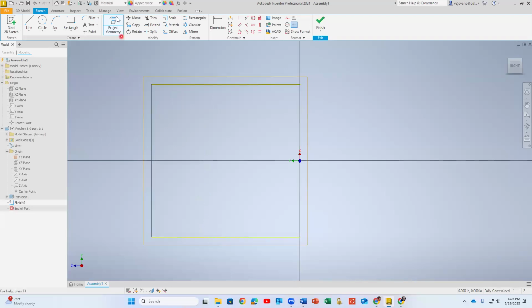And then before I use them, I can turn this off by either clicking one more time there or Escape. So you see, I no longer want to do that, or you click somewhere else on something else. So what I want to do is switch what I projected to construction line, because maybe it's just showing me projected geometry. Okay, now it's projected geometry.